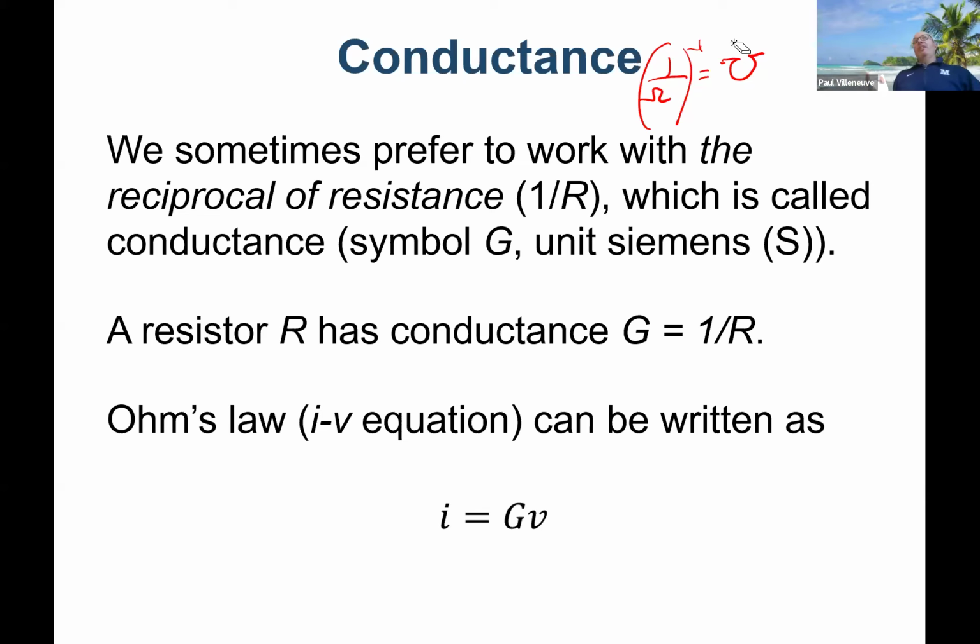So conductivity measurement is a way of telling you how clean the water is. And you can't be too clean and you can't be too dirty. So you're trying to find a medium, and usually they have alarms. Hey, the water is at the right conductivity level, which just means how electrically conductive it is. So how do you detect conductivity? You run a current through it. And if the current has a certain value, its conductivity is really good. If it runs well, then its conductivity is really good, which means the water's dirty. If hardly any current flows through it, it might be too non-conductive, too clean of water, which can be bad as well. So you have to find that happy medium, and you do that all the time.